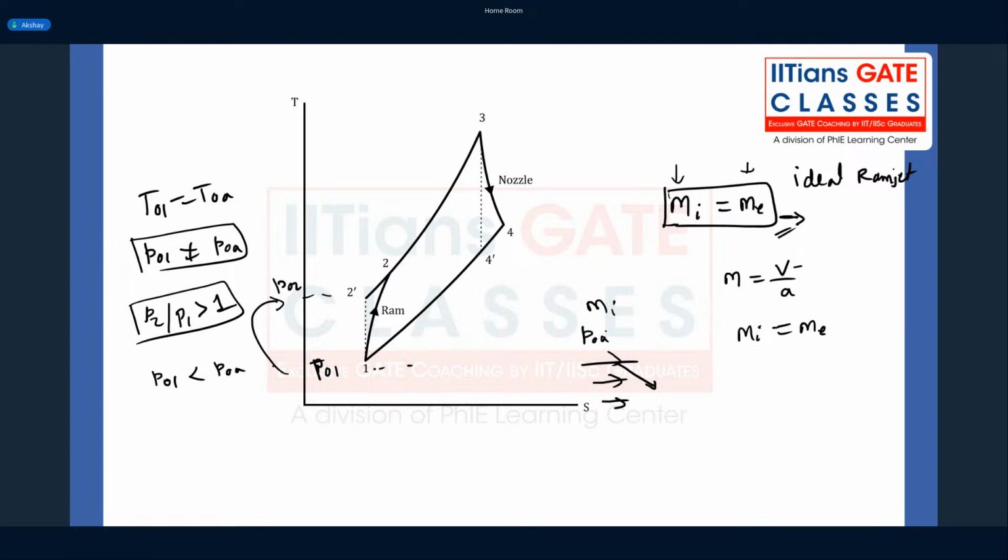So ideally, if you can bring this flow to zero velocity, then the local pressure what you have, PA, should naturally increase to P1, that should be equal to P naught A in ideal scenarios. But in actual scenarios P1 is equal to P naught 1, which is not equal to P naught A. Clear? So you are increasing the pressure by decelerating the flow in the inlet,